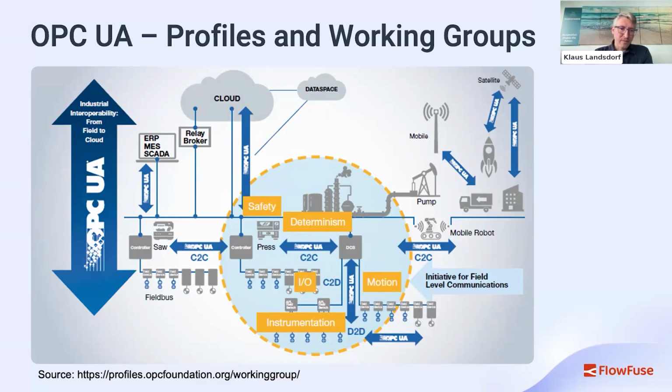You have security for Modbus, for BACnet, but also for OPC UA. The main benefit comes mostly when you use these specifications. There it makes a lot of sense for you to bring in OPC UA. Because if you think about Modbus registers, you have to check every time what the register is for, what the value is, whatever. How to combine all these 16-bit registers to get 32 bits, and so on.